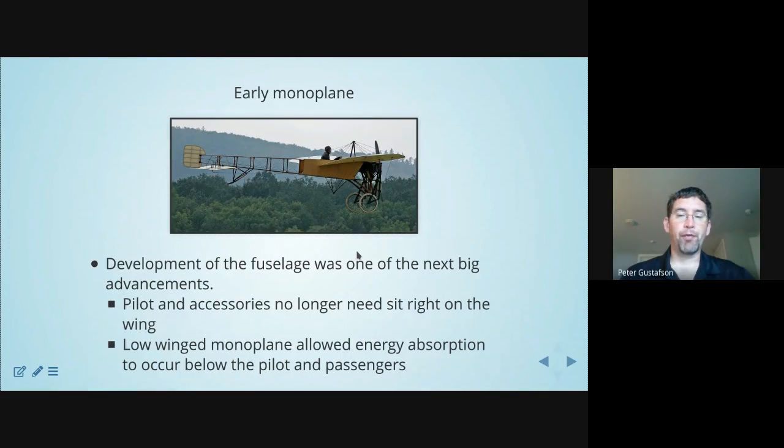Now, stepping forward a few years in aerospace engineering development, one of the things that came next in terms of significant structural change was the early monoplane. I had mentioned some of the advantages of flying in a biplane, or in fact triplane or multiplane configuration, the biggest of which is a decrease in the induced drag. Again, induced drag matters at high lift coefficients and slow airspeeds.